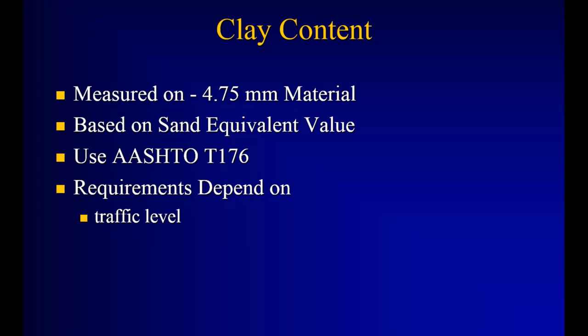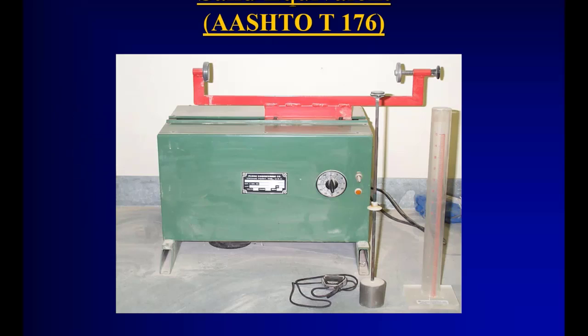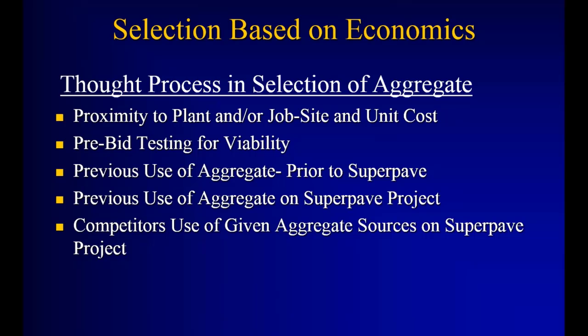And so after we've mixed it together, we've introduced the stock solution, agitated it in a mechanical shaker like this or a manual shaker. Once we let kind of the dust settle, pardon the pun, we can get a clay reading and a sediment sand reading right from the test.